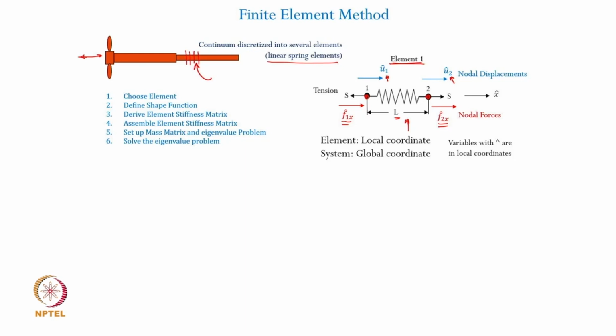Once we define the element completely, we are going to assemble these elements so that finally it forms the entire vibratory system. It's quite similar, as you would recall, to how we characterized each segment in a transfer matrix method and then looked at how the state variables of individual segments are interconnected, and then we formed a global vibratory system.